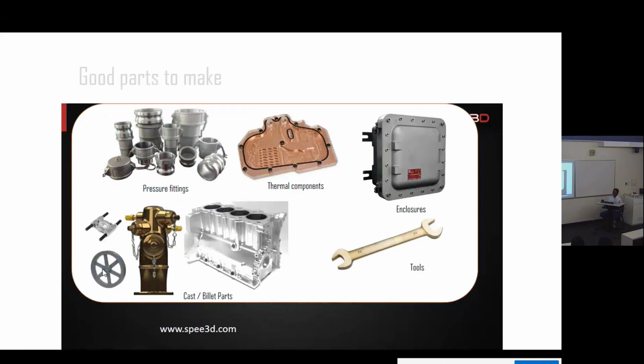So that anisotropy is actually lost in terms of the part being manufactured, which may be important for certain cases, but it's probably not possible for us to produce that kind of anisotropy. Otherwise, it needs to be designed into having materials with different properties. But directionality would be something that will be lost in this, whereas with casting, there is a certain amount of directionality if you don't do any heat treatment.